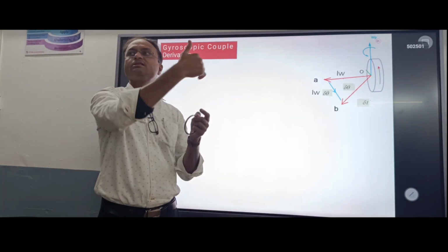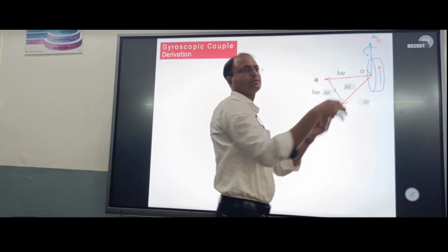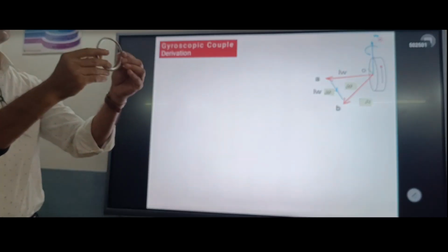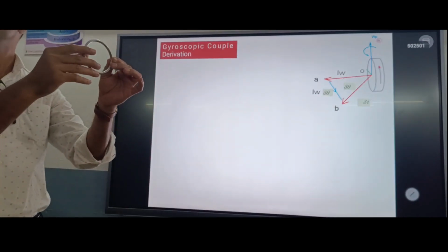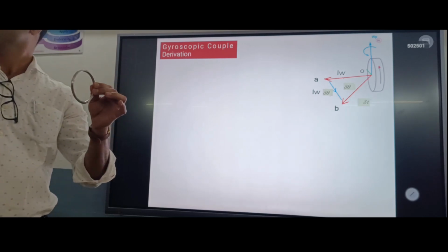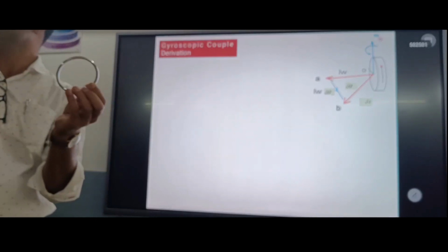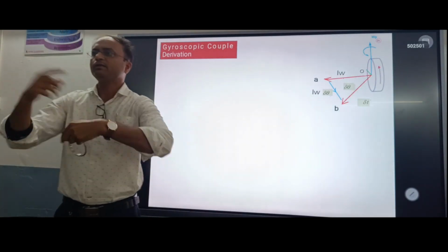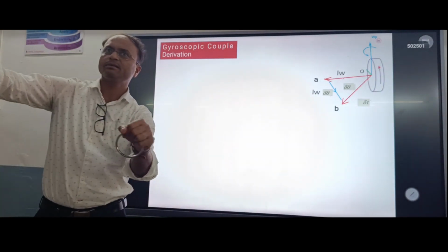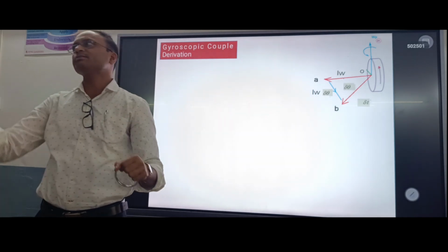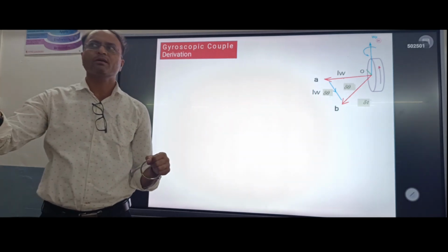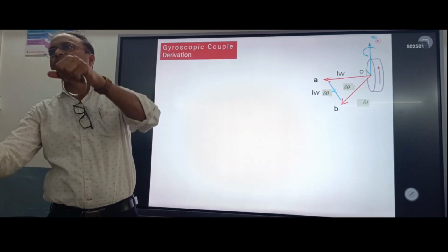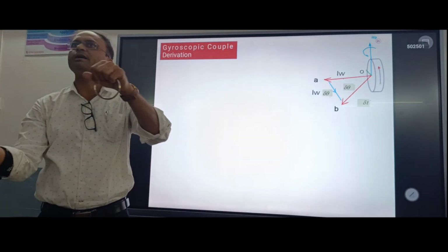Now secondly, when I turn it, first of all we'll see the turning effect. What happens if the disc is turned? So how is it turned? This disc is rotating like this, okay, and now it is turned in this direction. Just like you take a turn while riding a bicycle or a two-wheeler. How do you take a turn? The wheels are running like this, and if you take a turn, you actually experience that gyroscopic effect there also. How? The effect of this is that the vehicle tries to tilt to the other side. Am I right or wrong?